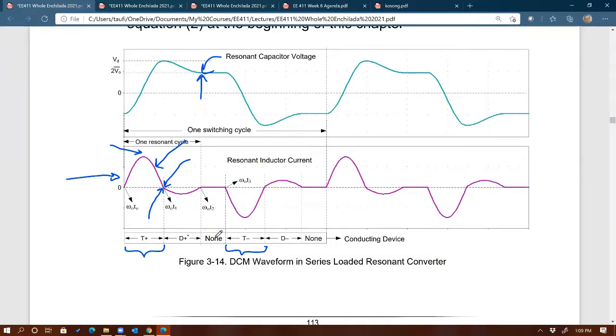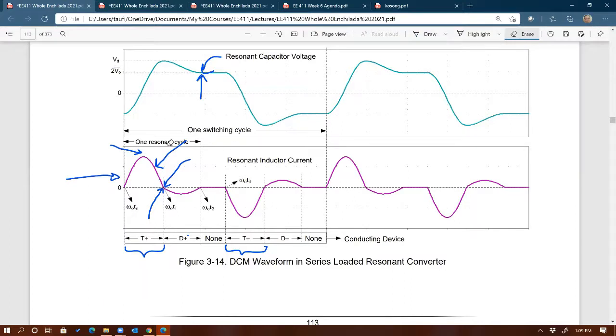You see that? Can you repeat what you said a second ago? Even if you're using a MOSFET, D plus will turn on. Are you talking about a unidirectional MOSFET? Yeah, it is unidirectional, right? Even though you have the diode across it, that diode is slower compared to this diode, D plus. So between the two diodes, D plus will conduct first.